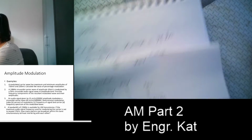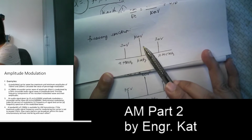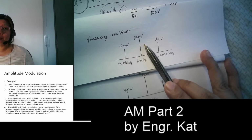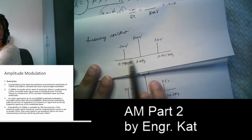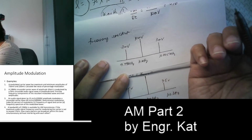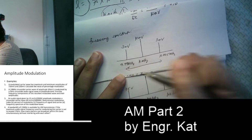So this is your spectrum. So this is your carrier with its unmodulated voltage. So this is 10 millivolts, and then your two sidebands here, and that is that they both have 3 millivolts as their peak value. Okay, so you may get the bandwidth. Although it is not asked in the problem, we can solve for the bandwidth. So this is your bandwidth.